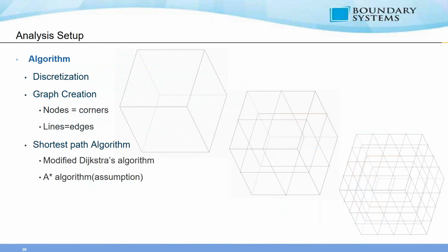Okay, so as far as the analysis is concerned, it goes in this type of process. First is discretization. This is the process of transferring continuous functions, models, variables and equations into discrete counterparts. In this case, the boundary box of the assembly is divided into smaller boxes, starting with a slightly enlarged outline of the boundary box of the assembly. That's what I have there in the first image on the left.